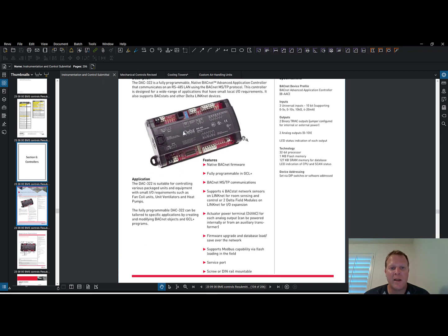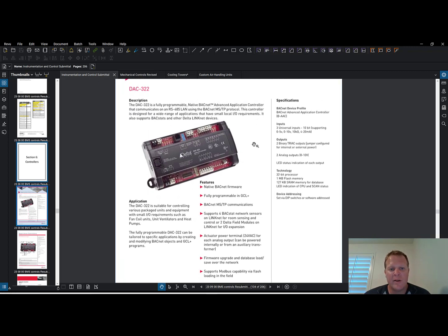I know that when we're dealing with that kind of stuff, the BACnet, all this, it's part of a larger building automation system, and so they need to be speaking together. If this is part of a campus or a larger system, again, this was part of a hospital, so it matters a lot that the facility people that manage the buildings do not want things that are not compatible with their existing systems. So I need to facilitate coordination between the mechanical contractor, the controls, and also the folks on the owner side that will be able to take care of this stuff. And those are things that I need to start doing early on.